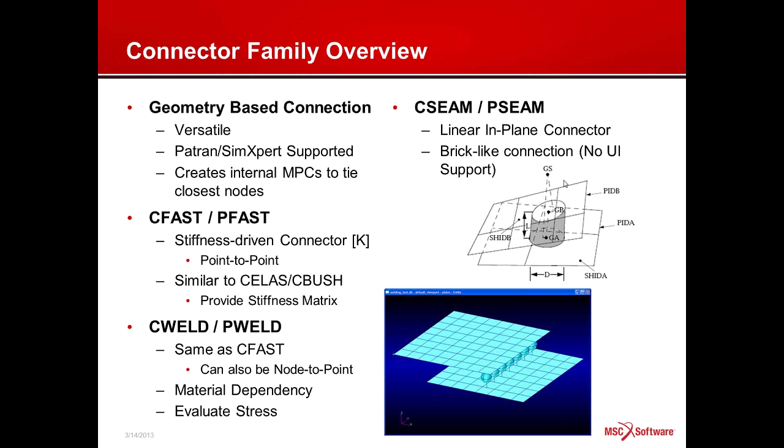So you can create a fastener by saying, here's the position in space, and find the two closest plates that are projected on, and it will attach those plates together. So the C fastener works a bit like the C bush element. So it's a 6x6 stiffness matrix. And you can actually punch the numbers for carrying only translational or only bending or both, typical of C bush.